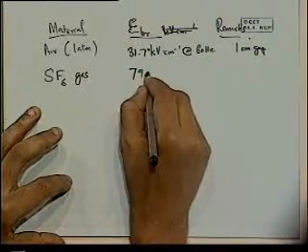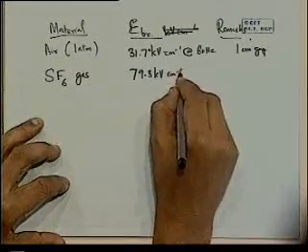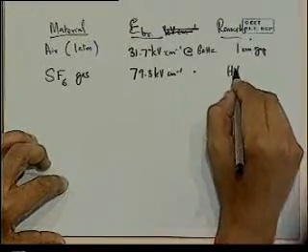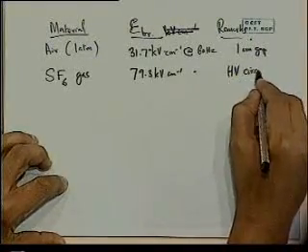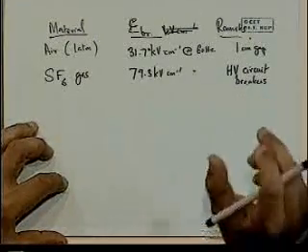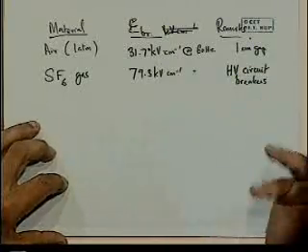So in this case, it can go up to 79.3 kilovolts per centimeter at the same frequency of 60 hertz. And thereby it is used in various applications, like I said, measurement, or in high voltage circuit breakers. Because as you see, when you pull out even a fuse, there's a spark across it. That's basically breakdown of the air, right? Momentarily, that happens. Now, when you're dealing with high voltage things, those sparks could carry quite a bit of punch in it, and it can destroy things. So if inside that, you can seal it off with SF6, then instead of air breaking down, you've got SF6, and it can sustain a higher voltage.